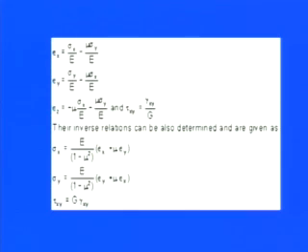So we can say the above set of equations, whatever we have written in the previous 6 form, can be reduced to a new form, because we are keeping sigma z as 0, tau xz as 0, and tau yz as 0. So the new form of these equations: first, the normal strain component in the x direction, epsilon x, is equal to sigma x by E minus mu times sigma y by E, because the minus mu times sigma z by E will be gone.